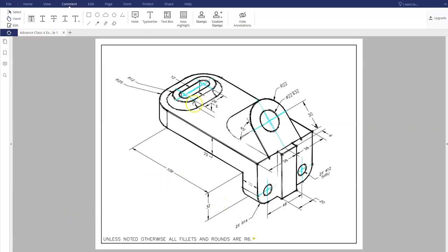Looking at this one, we can see we have a couple of dimensions that we're going to have to do a little adding on first. So what I'm going to do is add the 106 plus the radius of 25, and that's going to give me the entire length of this back line. Looking at the vertical side of this, you can see that it is 32, and we can assume, since it goes underneath the arc, that the height of this is 32. So once we're going to create this L shape, it's going to be the first thing that I will create